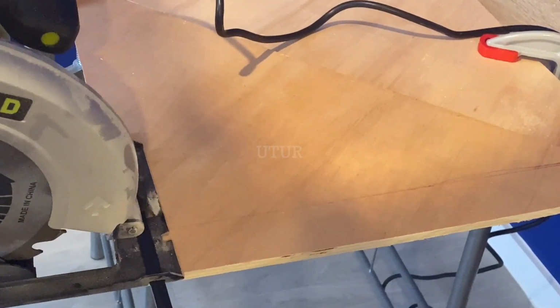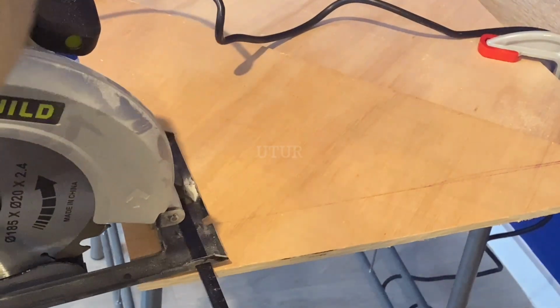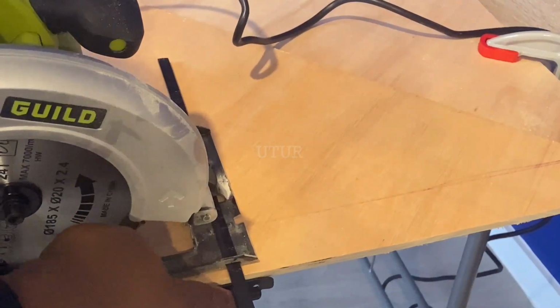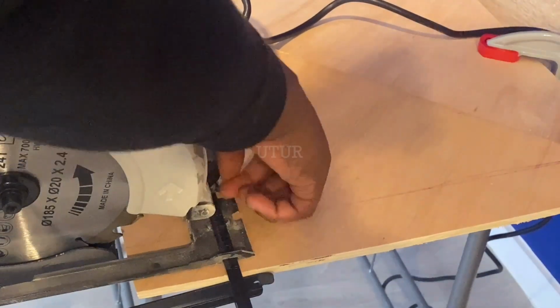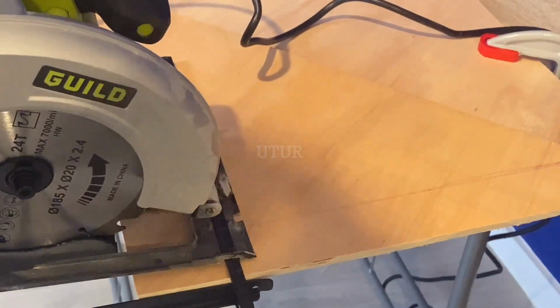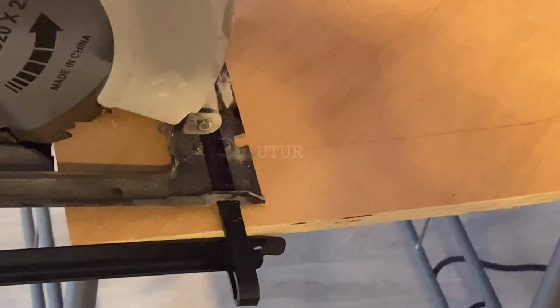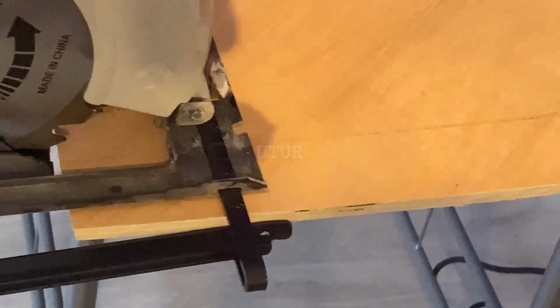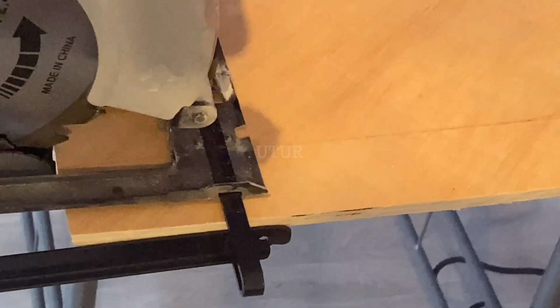So here I have taken cognizance of the fact that the plywood has been clamped onto the workbench. The edge of the plywood is flat, it's flush and it's straight. The lock knob has been locked into position after deciding the width of the rip, and I have also provided clearance for the blade to spin prior to latching onto the plywood. The cutting line has been marked onto the plywood as an extra pair of eyes to enable a more accurate cut when using the ripping fence or the parallel guide.